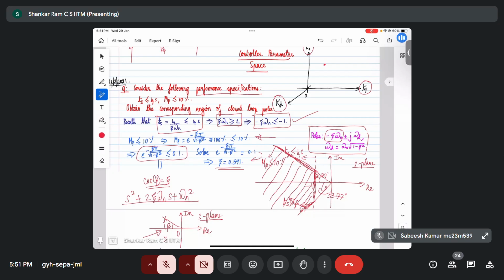So when you design a PID controller and take the dominant dynamics, you will see that Ti, Td or Kd, Ki and all will be related to zeta and omega n. That is the context in which those statements are made.